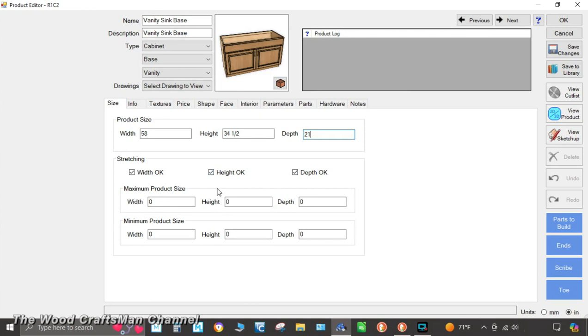For example, I had a job about a year and a half ago, coming up on 2 years maybe, where we had a tray-based cabinet next to a range, and I think that cabinet was 8.5 inches wide. Well, that leaves a 5.5 inch opening, which makes a really narrow drawer on the top. And what I found out is it's not that we couldn't make the drawer. It's that when it came to the guides and the locking devices, it was a pretty tight fit. And I actually got really lucky. The narrow locking devices for the Blum 563Fs just barely fit. So I actually had basically taken a single door with a drawer base cabinet, and I set it to have a minimum width of 10 inches, and anything under 10 inches it forces me to choose a different cabinet, and that's where I create a cabinet where it just has a door.